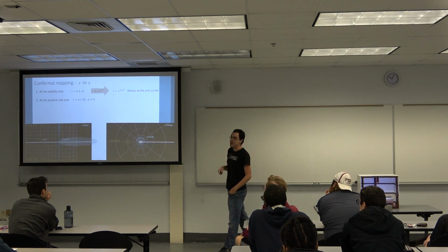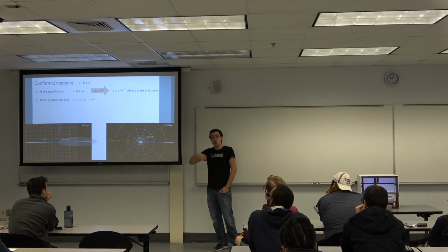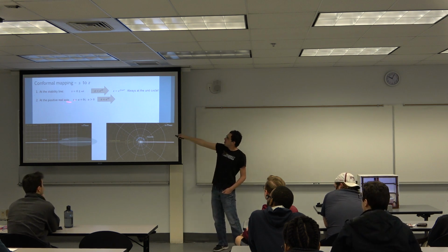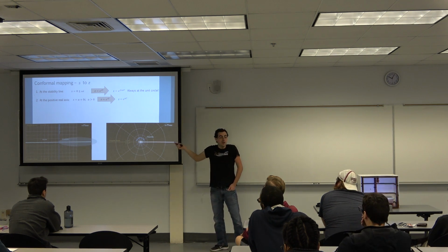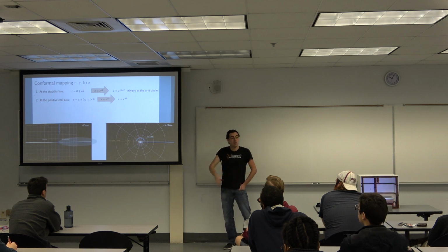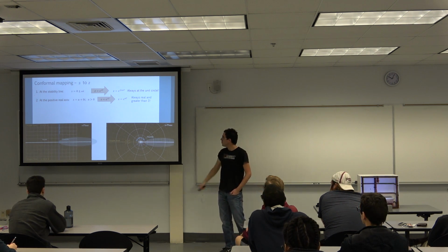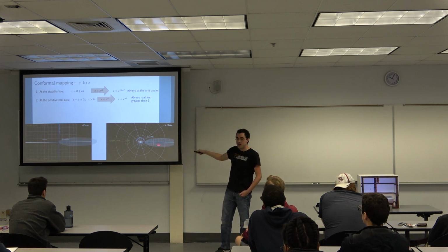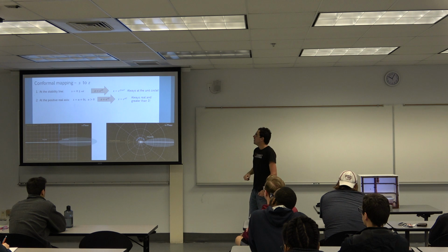Okay, this is kind of the easy part. So if we now look at the positive real axis, where we have exponential growth, but we don't have any oscillations, right? So what happens is, s is a real number plus no imaginary part. So z equals e to the st is just z equals e to the at. And e to the at is an exponentially growing number, but it's real. And it's always greater than 1 because a is always greater than 0. So this means that it lands on the positive real line, but always greater than 1. So this line here ends up over here. And you remember the mapping, it kind of folded. It didn't really move, it just shrunk a little bit.